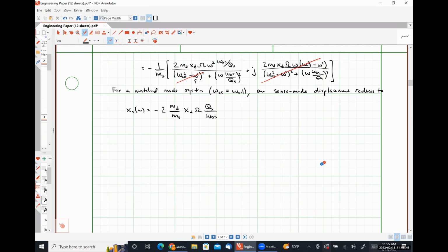So that means that we either have to physically trim our springs, meaning we have to go back through and literally laser etch to make sure that our spring constants and the ratio of spring constant to mass works out perfectly for both the drive and sense mode, or we have to include extra circuitry to electronically trim or match our vibrational modes, right? So this is absolutely a possibility, but it's typically more expensive to do it.